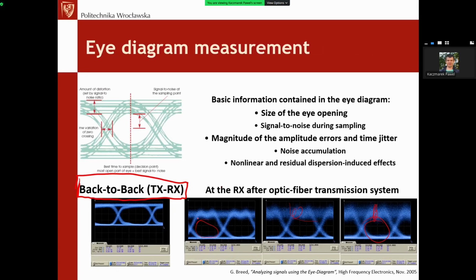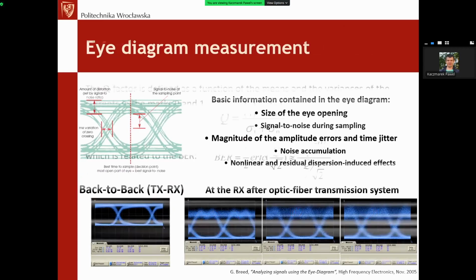Also, regarding some issues, you can see dispersion effects. These not-flat tops of the bits, but the hills here, are mainly because of the dispersion, because our network wasn't dispersion compensated. It was only 60 kilometers, so the dispersion management wasn't so important in this network, but it appears on the eye diagram quite easily.